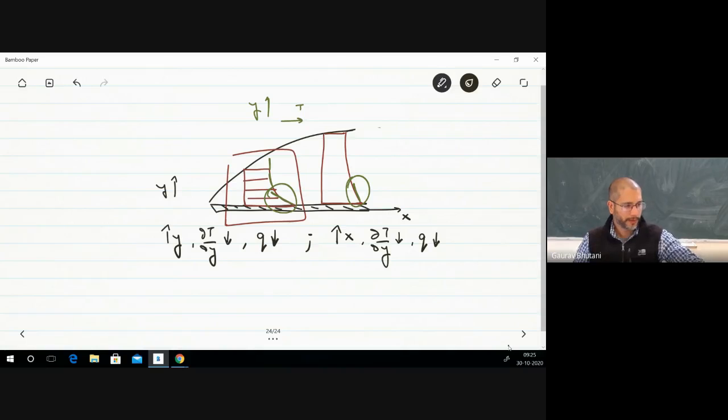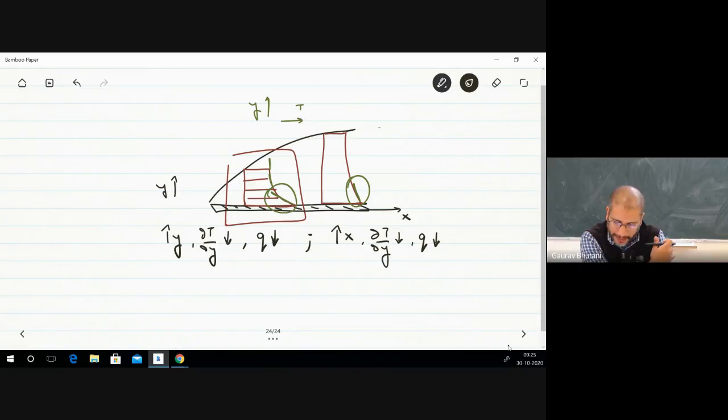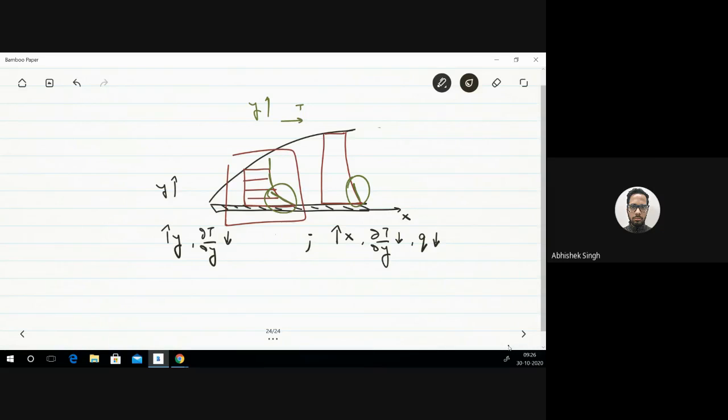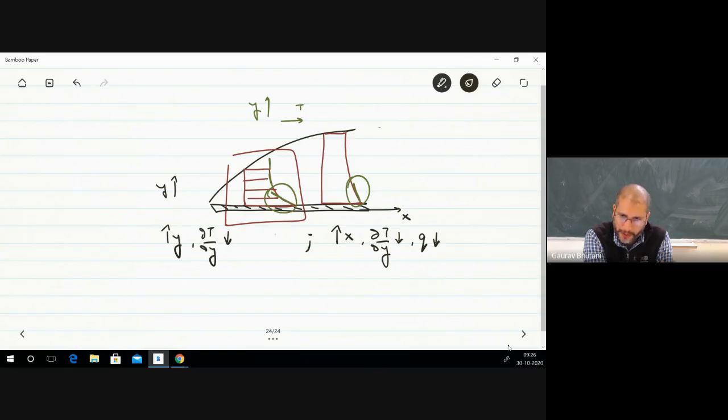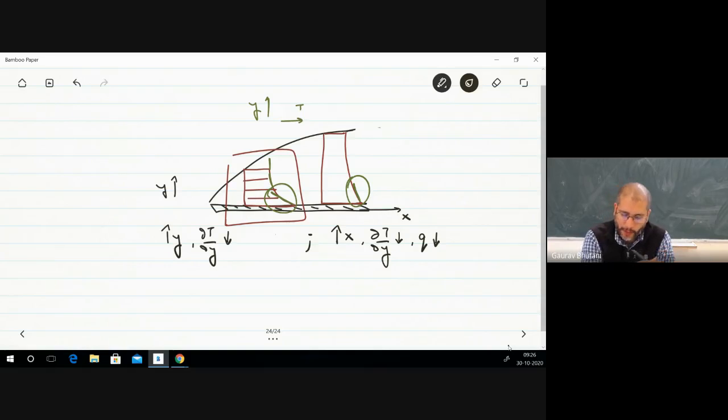Any questions? Sir, here the Q is defined at y equal to 0, but if v is increasing, right. Right, so that is the reason I was a bit reluctant to talk about Q here. Then we will have to consider velocity also, and gradient of T, something like that. The convection part of the differential equation, like v into dT by dx kind of thing. So now that I've removed this Q from the picture, is that part clear?